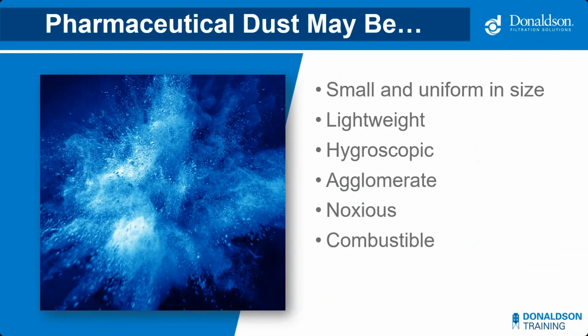Let's talk about the common characteristics of pharmaceutical dust. Typically, it is small and uniform in size, lightweight, and hygroscopic, meaning that it attracts moisture. So any wet applications or introduction of moisture to a process could cause a particulate to become sticky, and then it dries in a hard crust that can be difficult to manage from a filtration standpoint. It can blind off filters and create issues.